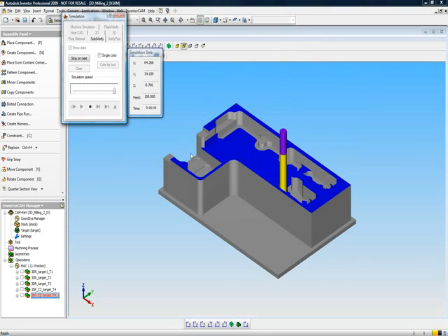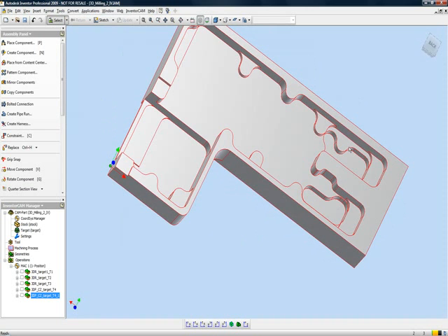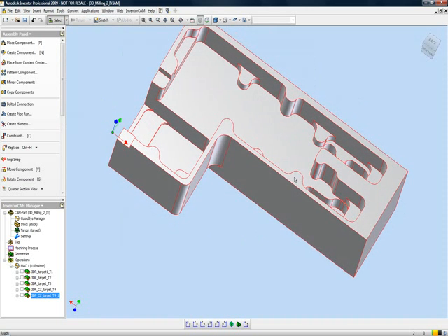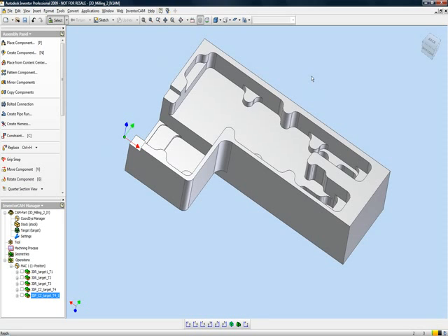Finishing up the entire part, we've basically machined our entire prismatic part using 3D operations. One of the major advantages is that I do not have to deal with each one of these pockets individually. It automatically picked up the entire part and did this within very few operations.